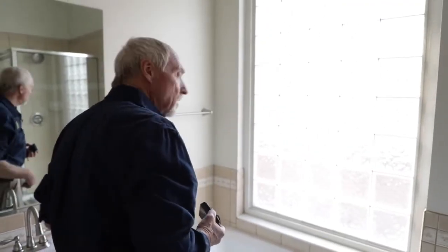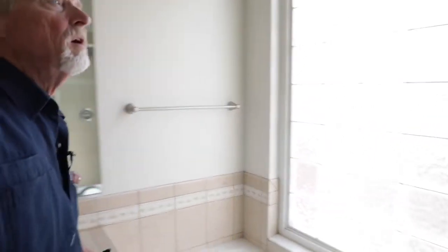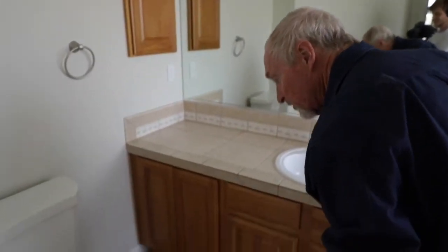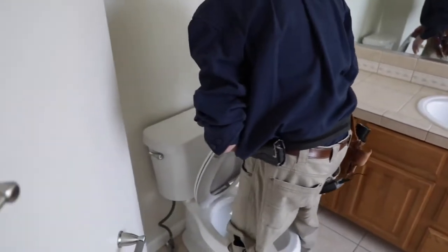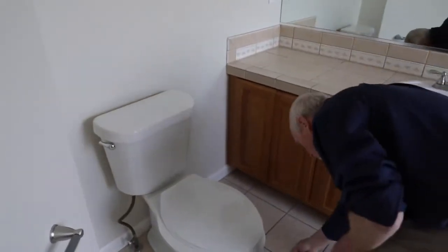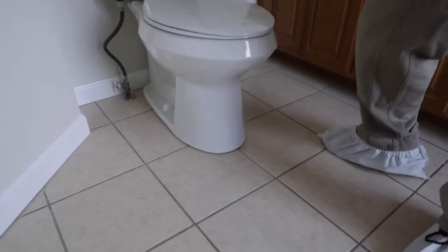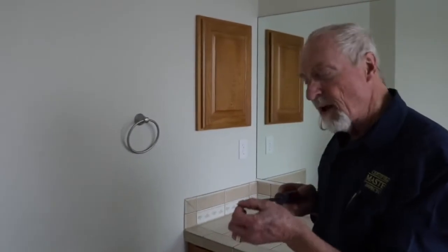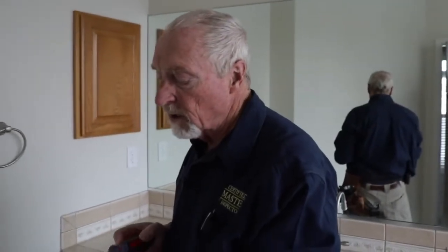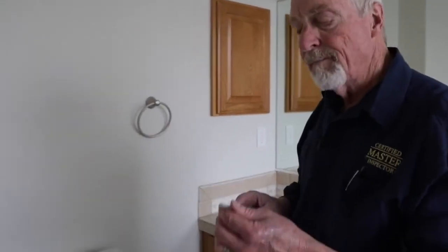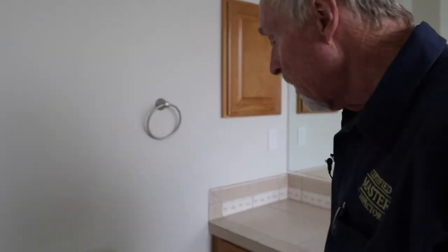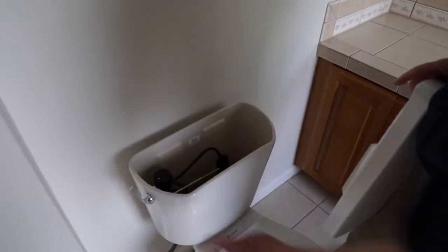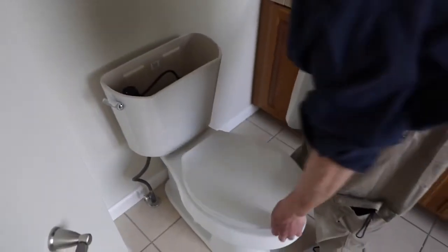I'm looking at my window here, which looks pretty good. And so now back into the regular routine here. Check the toilet. I'm going to check and see if it's nice and tight. It is. Take my big screwdriver, check the bottom, see if I have any caulking hiding under there. I'd get a dull kind of feel, and I'd feel it squish against the caulking if it was caulked underneath. I don't get that. I'm thinking it's not sealed or caulked to the floor. I call it out. Take a quick look inside, of course. See how it flushes.